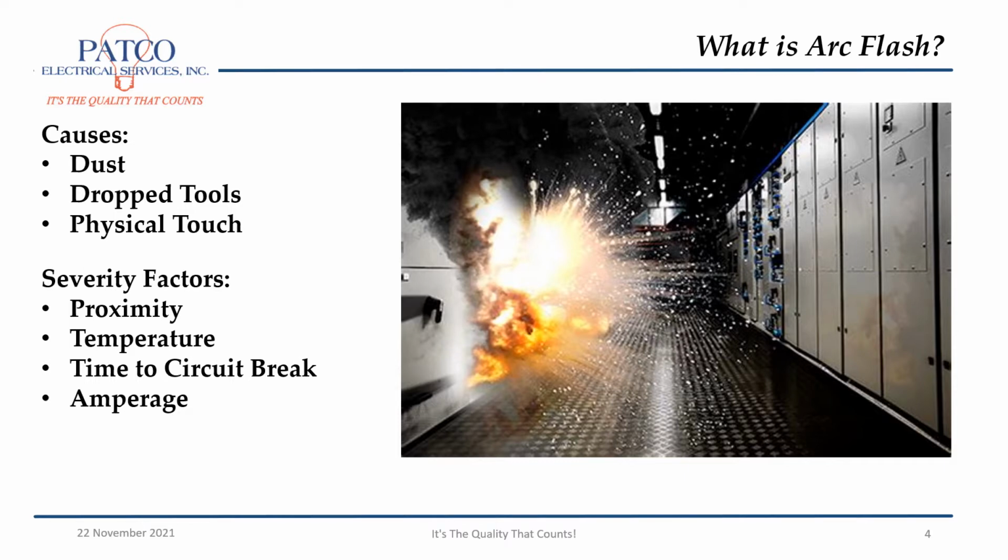Causes of arc flash can be dust, a dropped tool making contact with two different circuits, or physically touching circuits. Severity factors: proximity, how close you are to the blast, the temperature of the fire coming out, the time it takes the circuit to break, and the amperage.